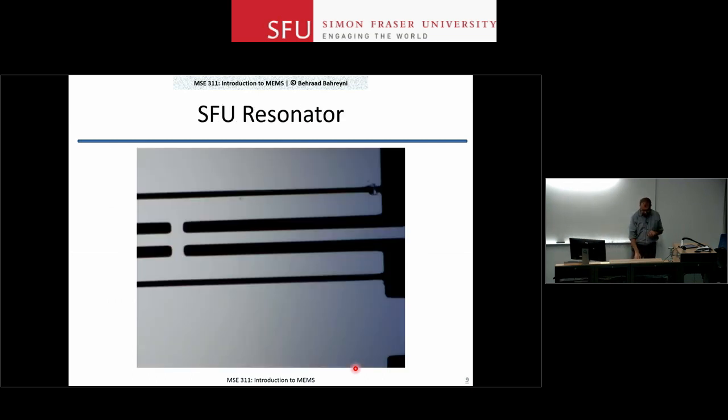Now, here is what can happen during pull-in in real life. It was unlucky for the device, but it was lucky for us that here the researcher was testing this electrostatic device. They're applying a high voltage to it. Everything looked okay. They played with the DC voltage on the power supply a tiny bit, and you'll see what happens if it is running. So all of a sudden you see damage appearing on the top electrode.